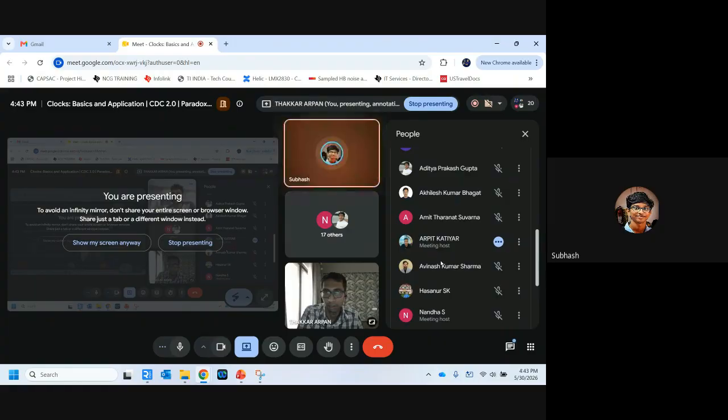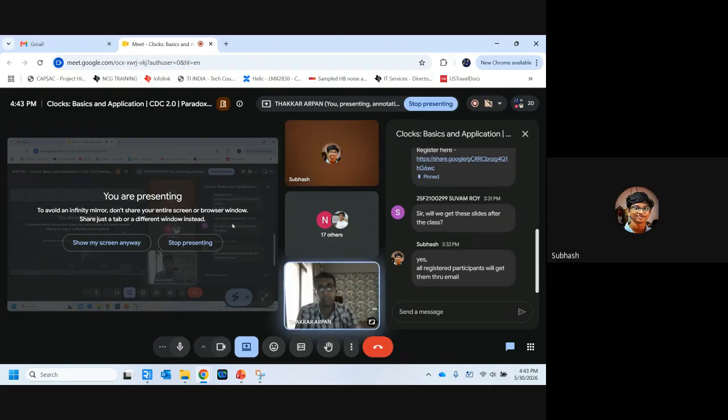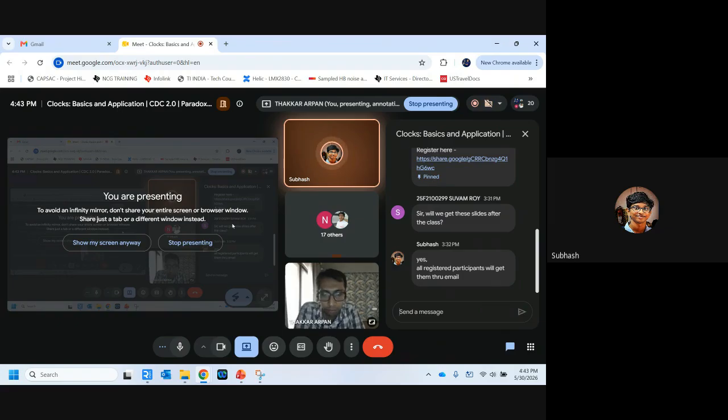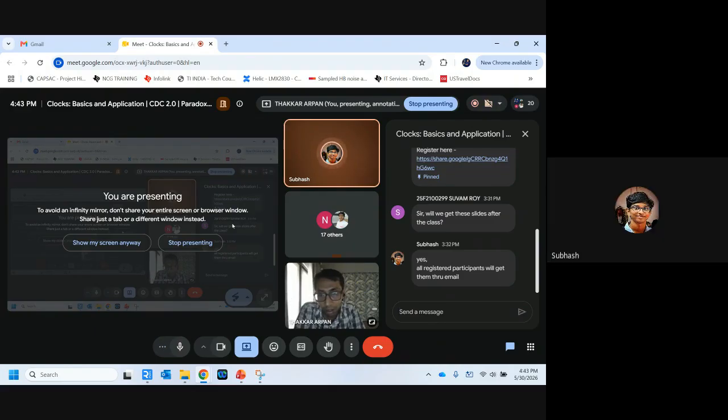So I have a quick question. I'm not sure how clear my voice will be. Am I audible? Yeah, your voice is audible. Okay, so basically, when we have the option of frequency multiplication, we can increase the frequency. I don't know how to even frame this question, but it feels a little bit counterintuitive when we have that option to even use any crystal oscillator. We can make some simple circuit with low frequency and then multiply it. Right? I mean, what are the downsides we'll face?